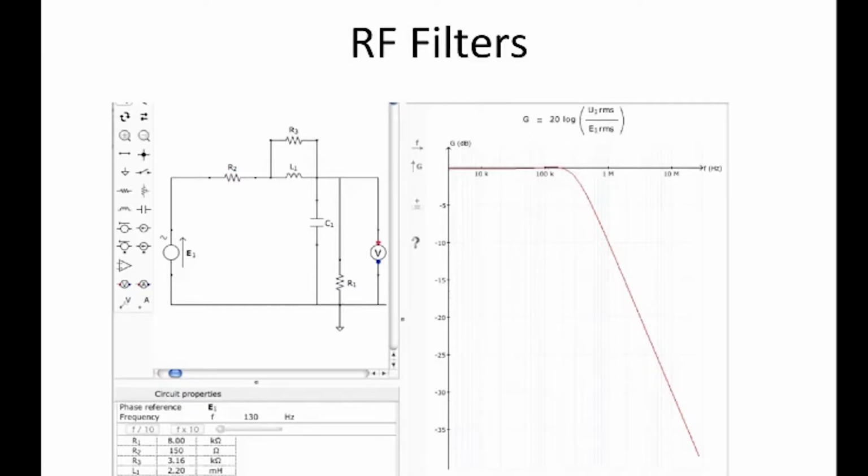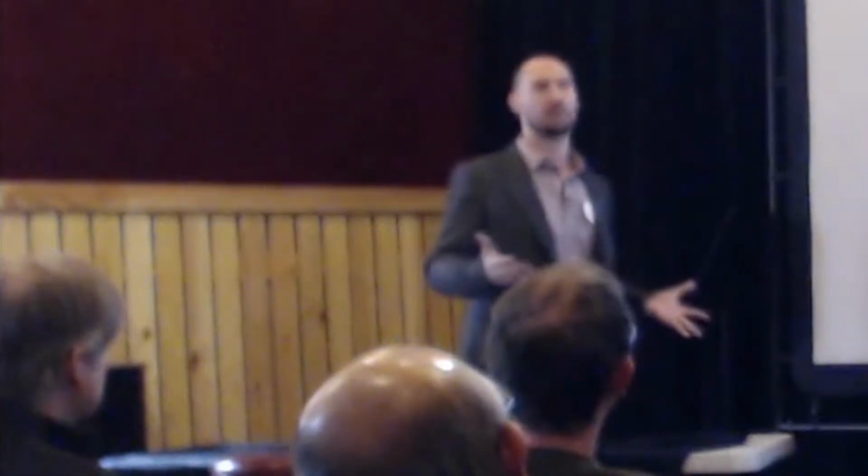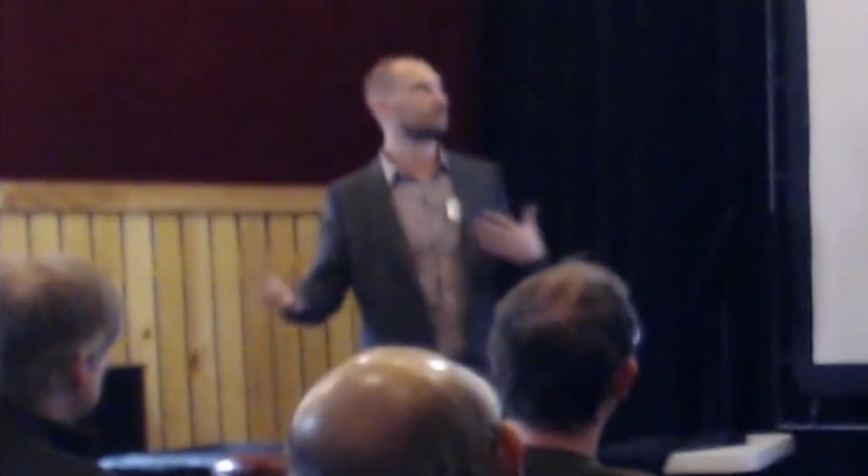the interesting thing about having to design this filter at the input to a mic pre is that you don't know what, well, in this case, R2 is, because R2 here will actually be the output impedance of the microphone that you're plugging into. Some microphones might have output impedances as low as 50 ohms, some as high as 600 ohms. So that's going to change the frequency at which the filter rolls off. And you have to bear that in mind when designing this filter.